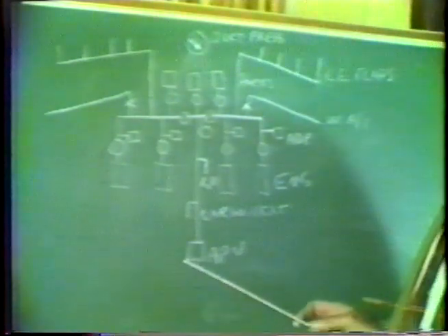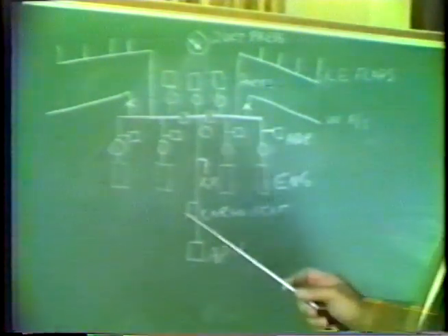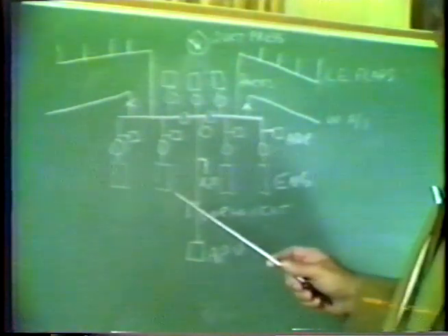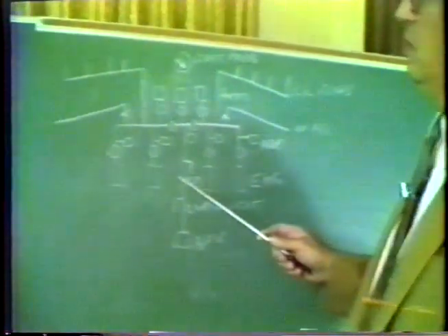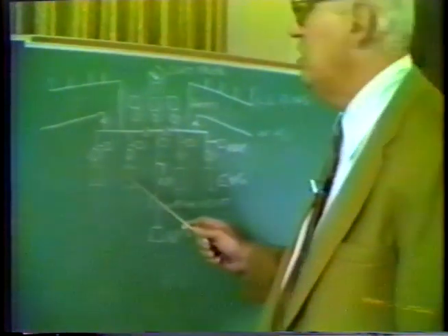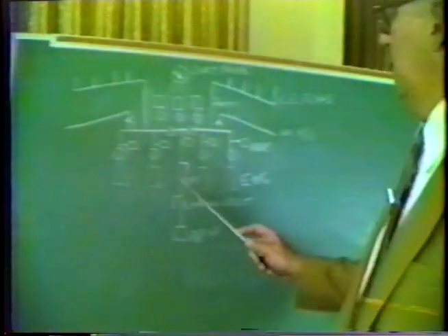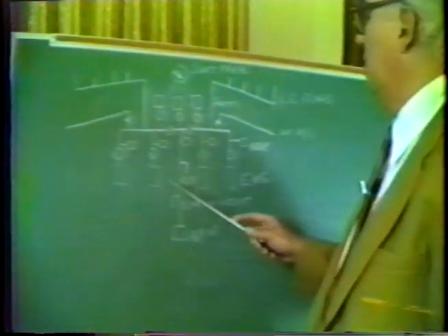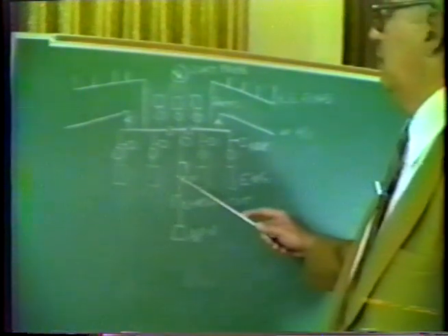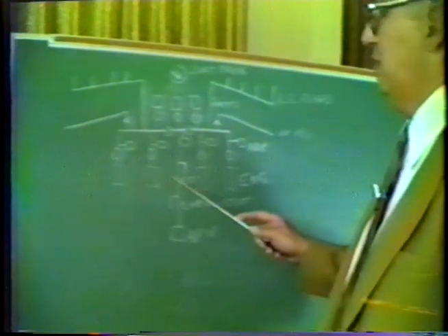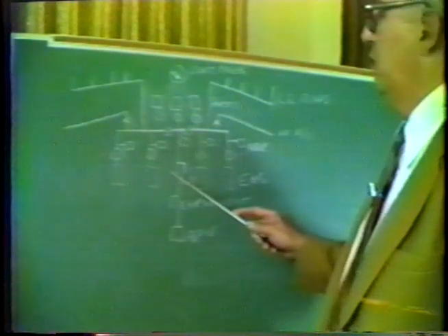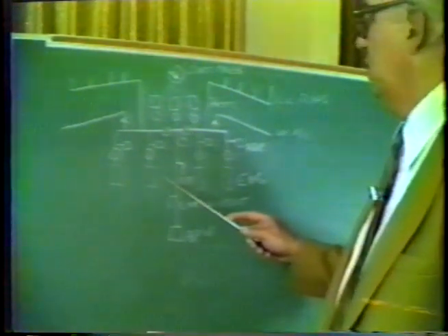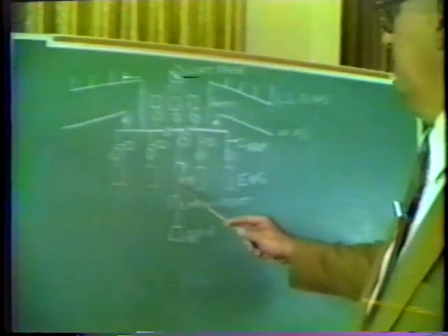When the high stage air comes in, this comes in at a time when the throttles are reduced. Normally it's necessary for descent. If the high stage air does not come in, then the low stage air would allow the cabin to climb when you're trying to descend, rather than pressurizing it, bringing it down to airport elevation.